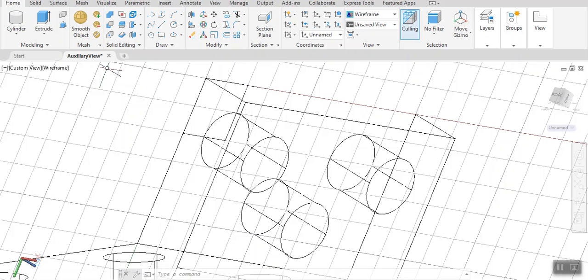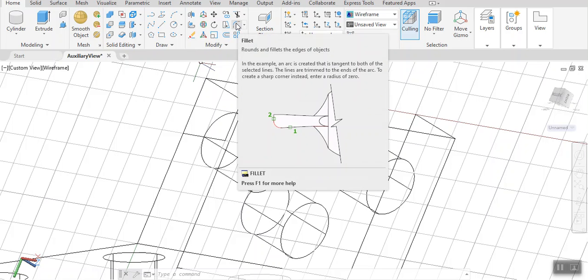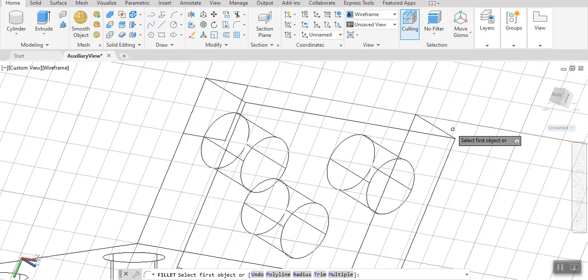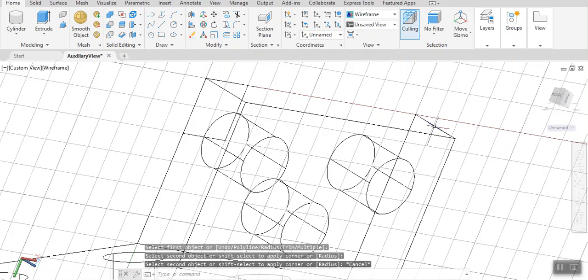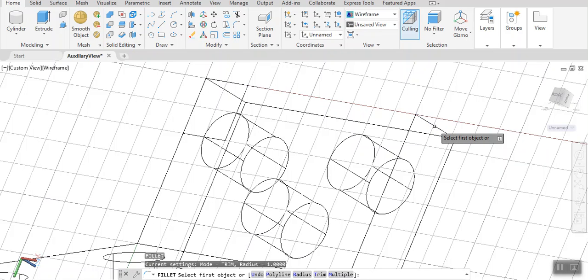What else do I need? Fillet command. I'm going to go to fillet and click on the fillet command. It's under the modify, and fillet is right under the trim command. Click. Okay. I'm choosing the corner and I'm entering the radius. All right, escape first. Subtract. Fillet command. R enter. And radius is 1 inch.